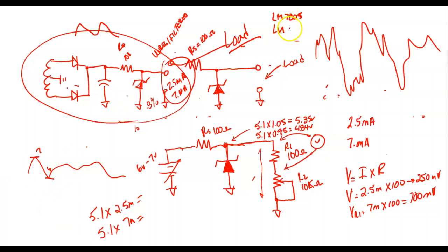It uses an LM, or it might not be an LM. It depends on the company. These first designators, by the way, usually are the company. This is the indication of the company that makes the device. So if you saw a DM7805, that would be a 5-volt regulator, and it would meet the specs of a 5-volt regulator.